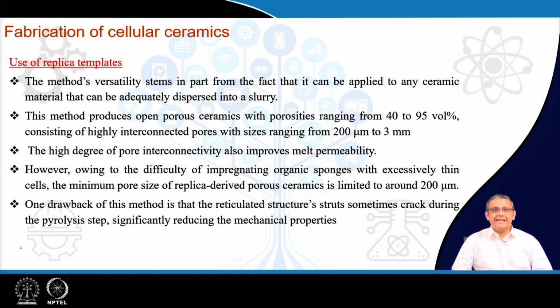One drawback of this technique is that these polymer struts and also the resulting ceramic coating on the polymer struts are very thin. So, sometimes during the heat treatment process they might burn, and that might give rise to some cracks or defects inside the structure, which can reduce the mechanical properties.